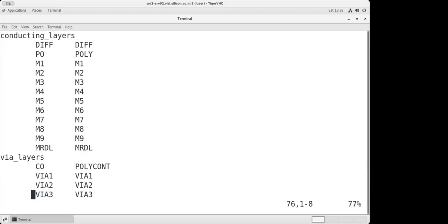Now, if you go with this metal 1, metal 2, metal 3, and you write out a GDS based on this, and you give that database to the foundry, they will not be able to recognize it because it's not as per their requirement, and they will not be able to fabricate anything. So then the concept of the map file comes into the picture. Map file in the sense of any two tools, or a particular tool versus the GDS. So you have to write that particular part.